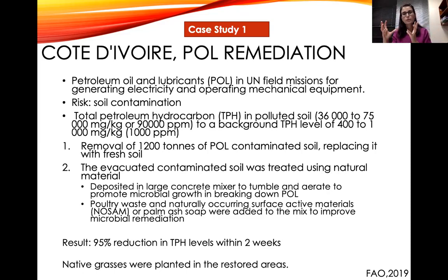So the topsoil was removed, put in a concrete mixture, and then the next thing that you do is you give food to whatever's degrading it. So let's say if the chemical is able to degrade or oxidize in the presence of oxygen, you would just expose it to air. But in this particular case, it was microorganisms. So to increase the concentration of microorganisms, you need to give them good food, right? So phosphorus and nitrogen and carbon and all of that.